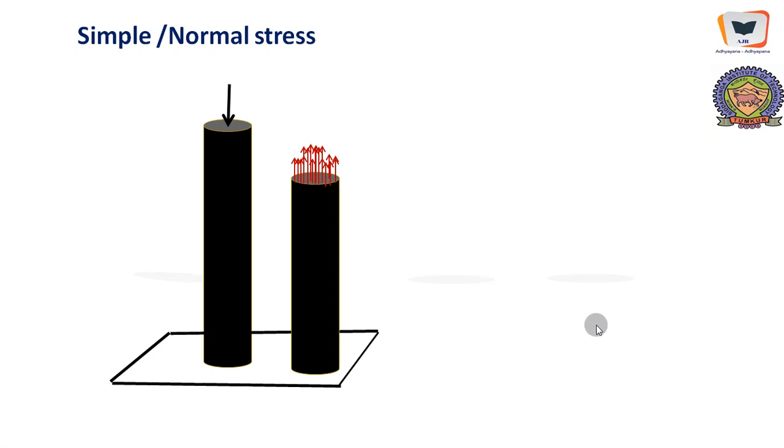Of course, there is a theorem depicting exactly when the stress, the resistance offered internally by the body, will be uniform in nature. We have to move far away from the application of the load. If we take a section somewhere over here, there is going to be stress concentration, and stress will be much more in the immediate vicinity of the load or beneath the load, and it will simply get diluted as we move towards the edge. This is the scenario being displayed here.